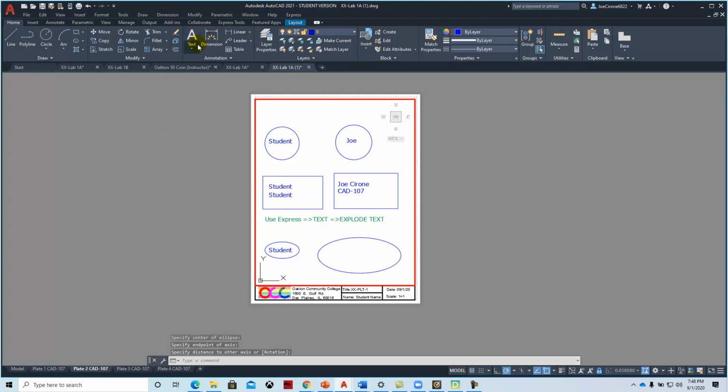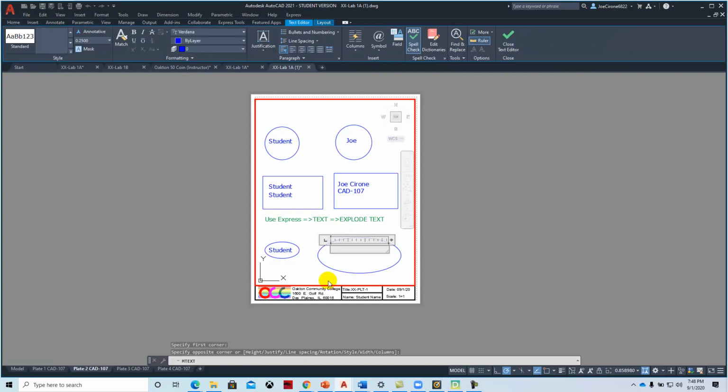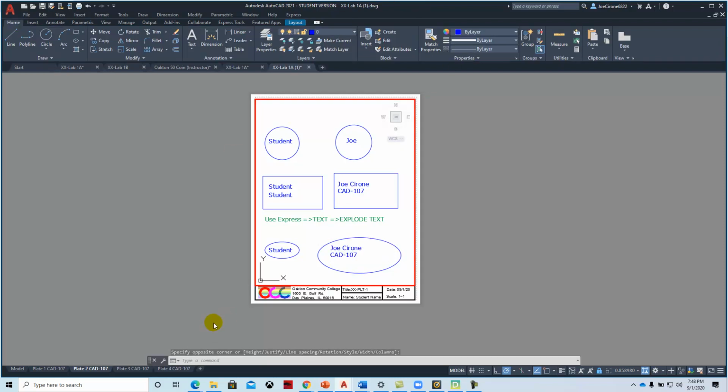And then I can put text on it. I'm going to hit escape because it had this O snap on, and that's why it is snapping to the center of it. So if I turn that off and then I do multi-line text, it won't try to grab the center point. And I'll say like that. And again, you can move it to the center with a grip,